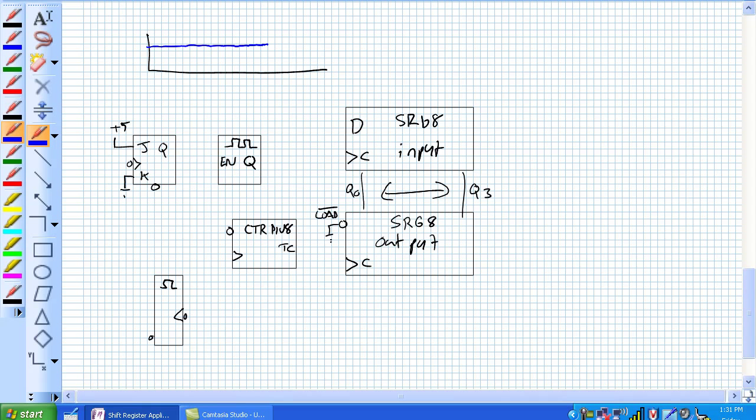When we want data sent, there's going to be a high to low transition and there's going to be a start bit, and that start bit is always 0. Well, obviously high to low, it's going to be a 0. Then the data can take whatever form it wants to, from 7, 6, 5, 4, 3, 2, 1, and 0, i.e. 8 bits.